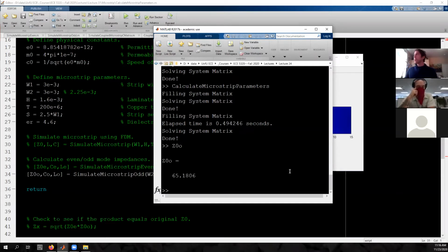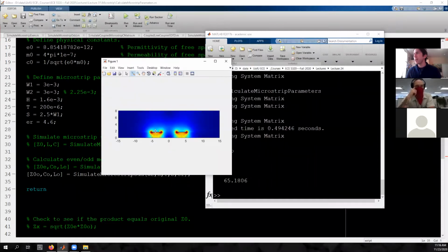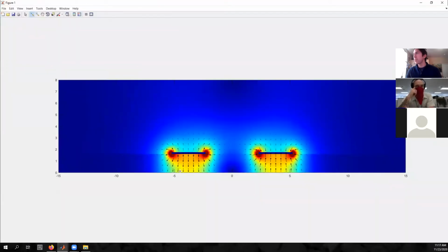And you can probably do a similar kind of hand-wavy argument about the capacitance now. It's not between this plate here and ground, it's between this plate and that plate there with this sort of floating piece of metal next to it. If you imagine two parallel plates, one above the other, you have a lot of capacitance. If you make them side by side, that will reduce your capacitance significantly. And then by similar arguments, your inductance will go up. And so your impedance is all going up at the end of the day.